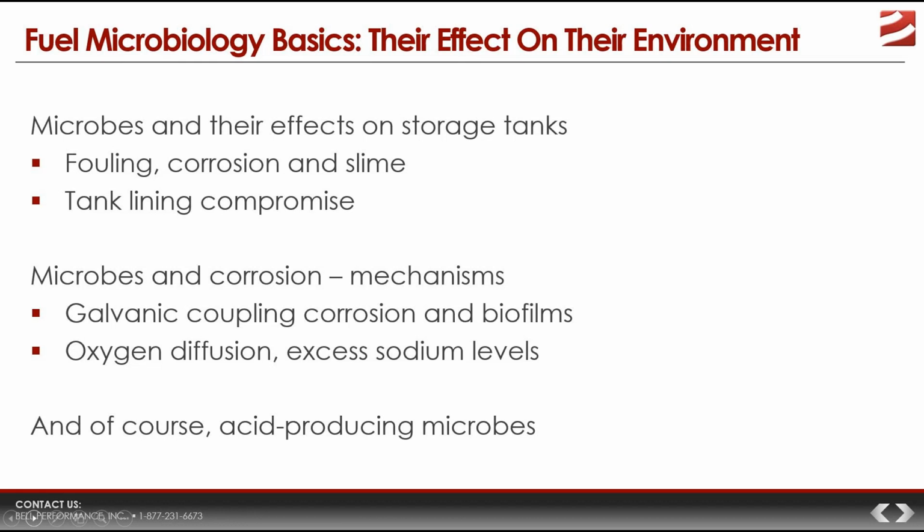Same thing can happen if there's carbon dioxide, that can form carbonic acid. If there's H2S, if you've got sulfate-reducing bacteria, that can help produce sulfuric acid. If you look at the tank water bottoms and you look at the sodium levels, if those are high enough, then those can react and form chemical soaps. What the chemical soaps do is they actually deactivate the corrosion inhibitors in the fuel itself. So there are multiple mechanisms for corrosion to happen in these tanks.